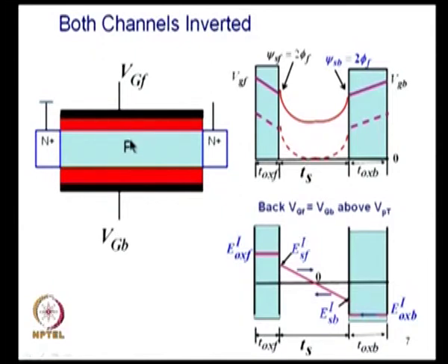So, electric field in this particular direction, this transverse direction, will be reduced by reducing the doping, by reducing the thickness. Okay. Now, you may question, if I reduce the doping, will I have a short channel effect? That aspect we will address later.